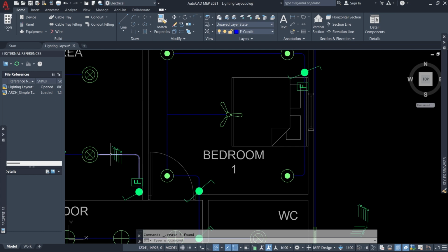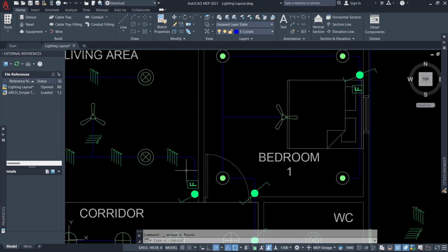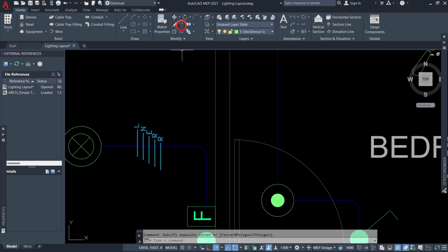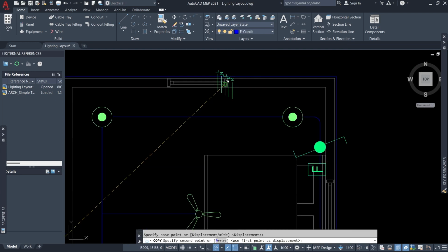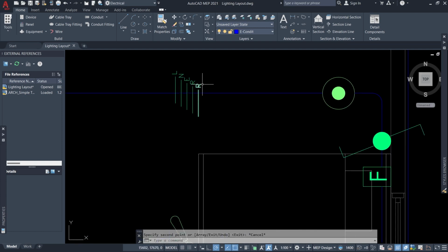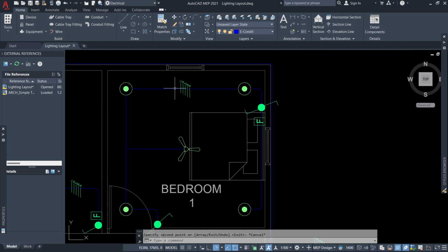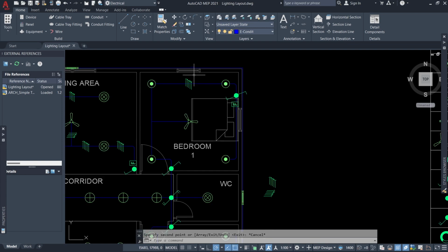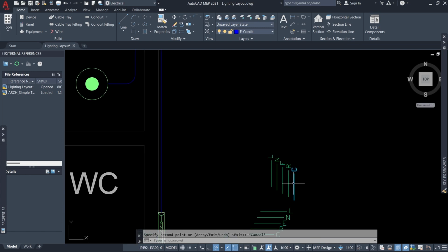Okay, so now let's go to the bedroom number 1. Now, something interesting is happening, and I want you to take note. This is true because the power comes to this place and comes over here. Okay, but let's look at something. It is true. At this point, we have 2 return wires, one for the fan, one for the light. Right. But we have a switch here.